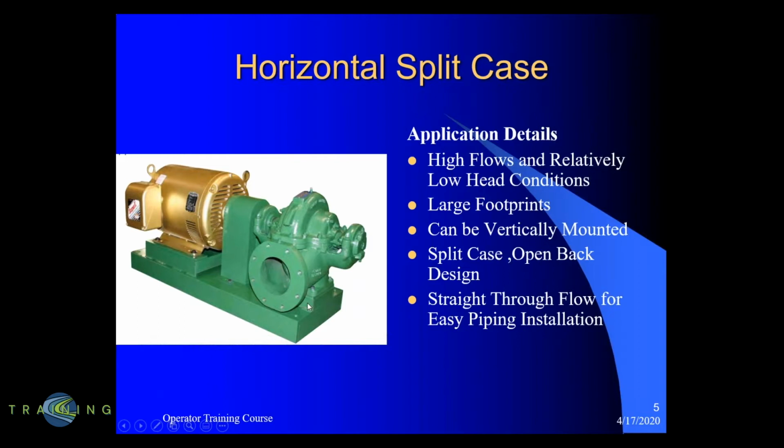You'll see these a lot in water plants, either for high service pumps if there are relatively low head applications, or backwash pumps a lot because you usually have fairly high flows in a filter and very low heads because you don't want to wash out the filter media.